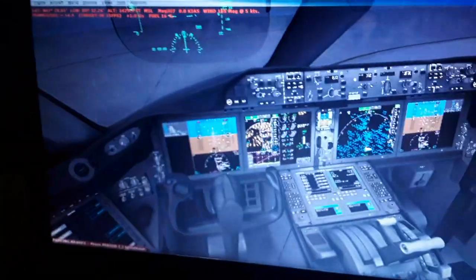We're also going to have, as you created, the flight plan using the flight management computer. I input all the data of the aircraft and the departure runway, that includes also the SIDs, the standard instrument departures, and runway waypoints and fixes. That includes horizontal and vertical waypoints and fixes for the initial climb, and altitude and airspeed constraints.